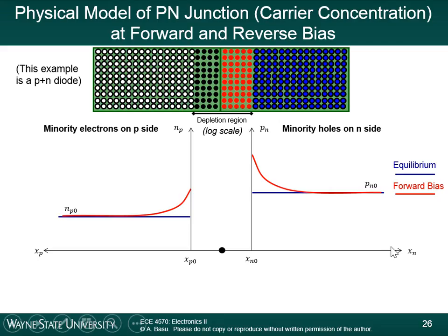Now, does this exponential relationship look familiar? Remember in the last module, when we were creating extra electrons and holes on the lighted side, you had excess carriers, and those excess carriers diffused over to the other side and recombined. We ended up with this exponential distribution. So this exponential distribution of holes comes from the holes on this side diffusing over. When they diffuse over, they recombine. That combination of diffusion and recombination generates this exponential profile.